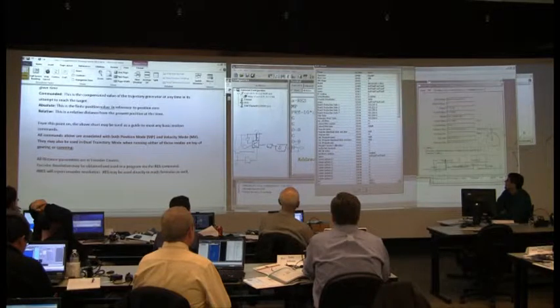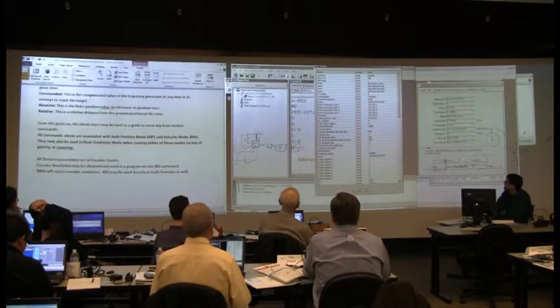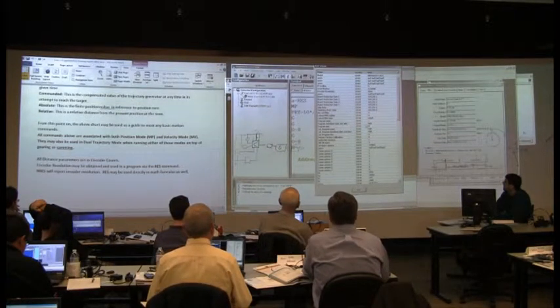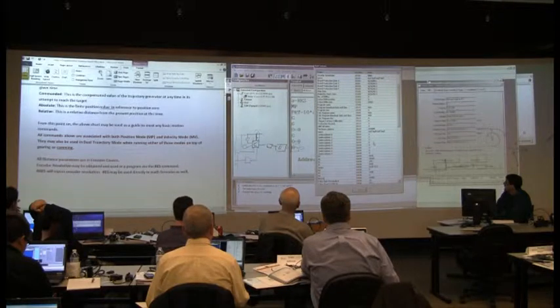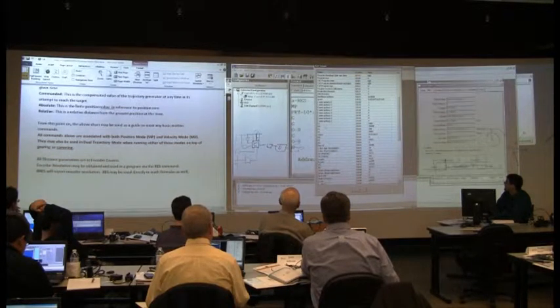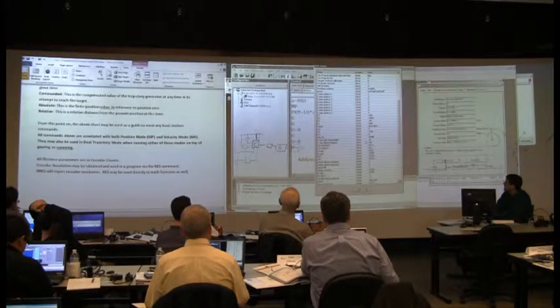You'll also see stuff like board production date, IP sealing, of course, encoder resolution, which, by the way, you can read from anywhere. Hardware options, COM options, and so on. You get down here and you'll find out our default tuning, KP, KI, KD, and so on.